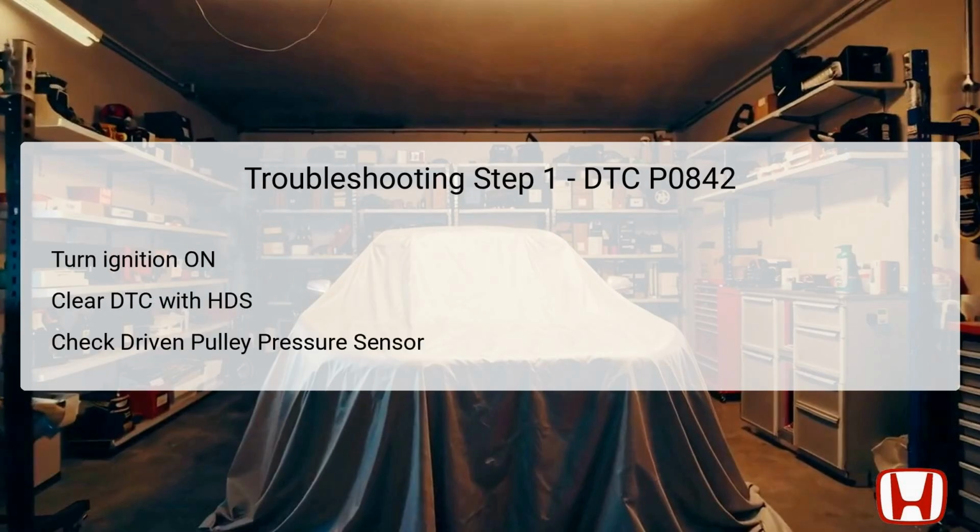The first step in troubleshooting the P0842 error code involves problem verification, setting the stage for accurate diagnostics. Begin by turning the ignition switch to the on position, or pressing the engine start-stop button to select the on mode. Once the vehicle is powered up, clear the diagnostic trouble code, DTC, using the HDS, or Honda Diagnostic System. This is crucial because it resets any existing fault memory, allowing for fresh testing.